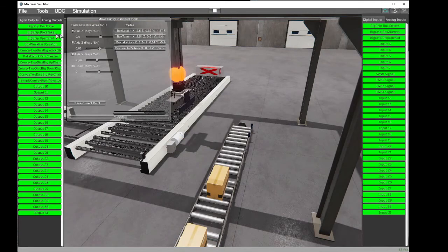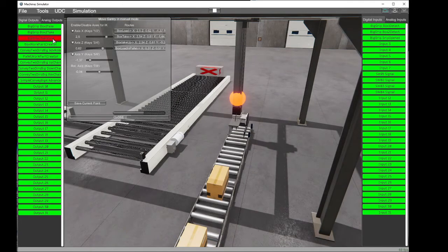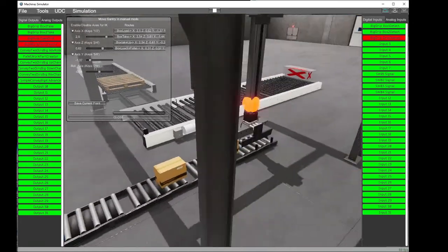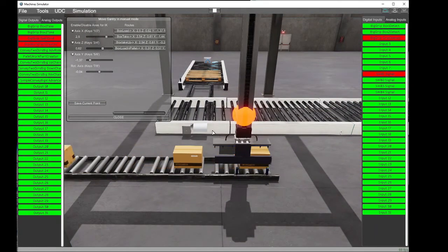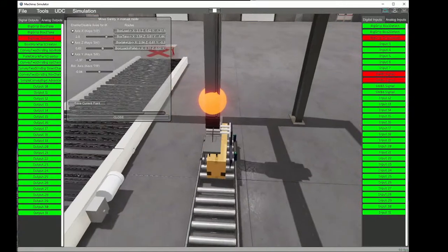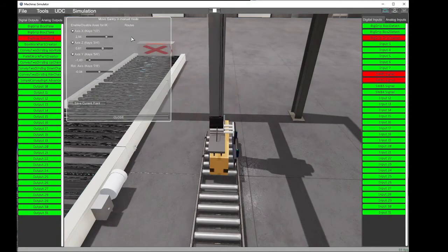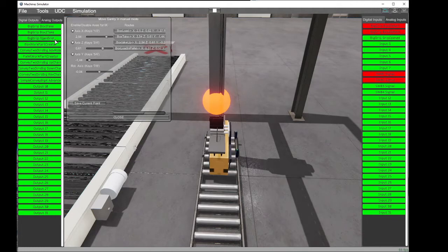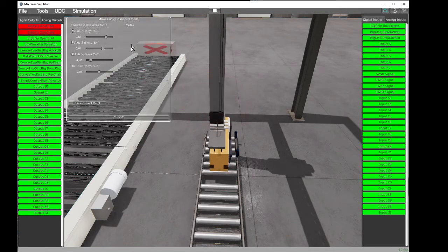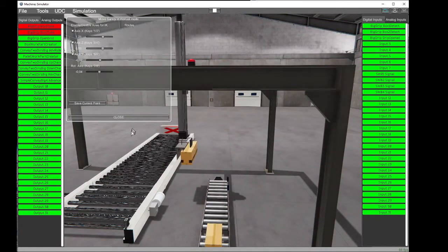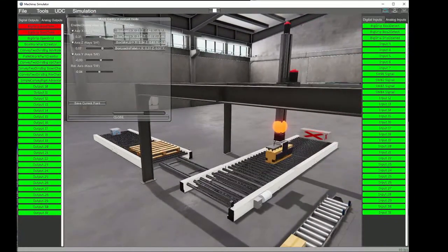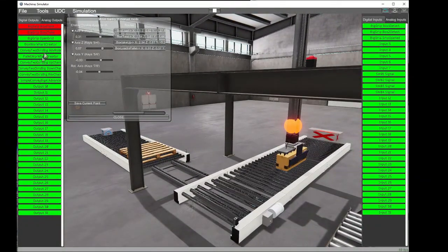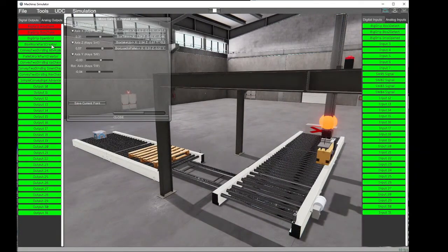Gantry in test mode. Let's move to the load position. Let's open the grip. Now connect the conveyor. The first box arrives, the second box arrives. Now we can stop the conveyor. Now we move the conveyor to the final, the take position. Let's close, let's activate the aspiration. We move up and we go to the download position. Okay, perfect.